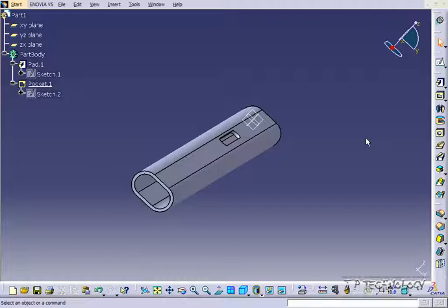Now, like in the previous tutorials, we're going to be using the compass to rotate. We used a rotate feature previously, and I'm going to introduce you to how to use the compass to rotate. For the compass to rotate, one thing I really have to emphasize is that you need to use a straight line and you need to position your line accordingly to get the best results.